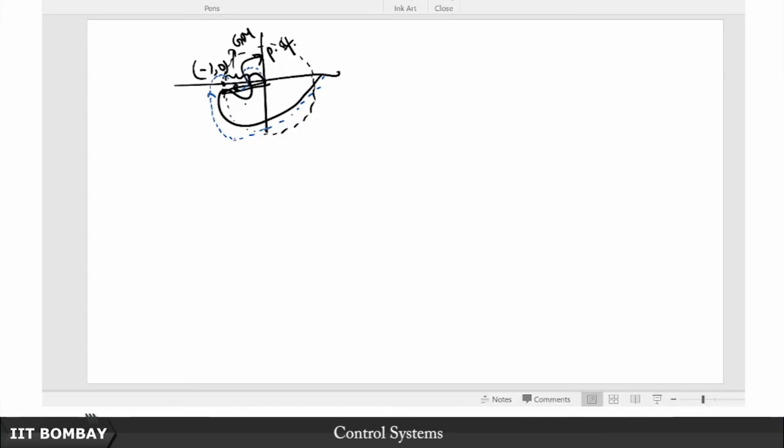So far whatever we have done here is about the open loop transfer function, but sometimes people might be interested in the closed loop behavior, because after all at the end of the day we put this transfer function in a closed loop and then we study the transient behavior, and then we want to find out what things like settling time, bandwidth, rise time, overshoot, resonant peak and things like that evaluate to. So we wonder, can Nyquist help us in that regard? Well, let us try and see.